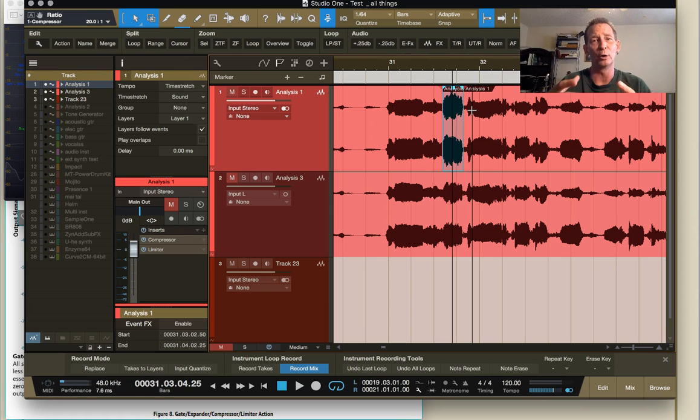Sometimes it's supposed to be a little bit louder in that section, so you've got to be real careful you don't reduce it too much. Then I'll go after it with a limiter, or I'll start compressing a little bit. You just have to be careful, because if you compress the dynamic range of those things together into the noise floor, that starts causing saturation from the noise and distortion in the lower levels of the audio. So be real careful of that.